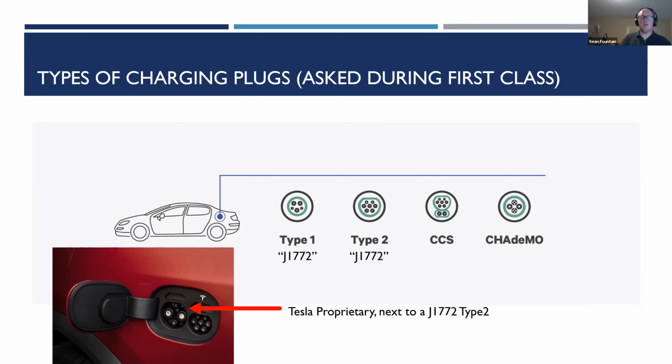In the case of type 1 or type 2, which are AC charging, they're still using the onboard charger, and it tells them how much it expects to be using. That's important because then the box goes, you're using more than you said, I'm assuming there's a problem, and it disconnects. It's like it unplugs your car from the wall, except with a switch. So most of these things are around safety. You'll find that you can't touch live wires in the plug that's on the wall side.